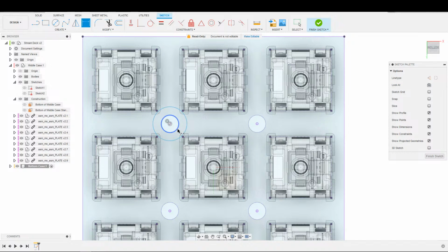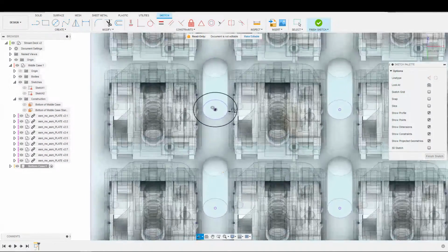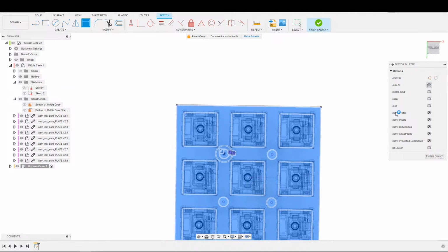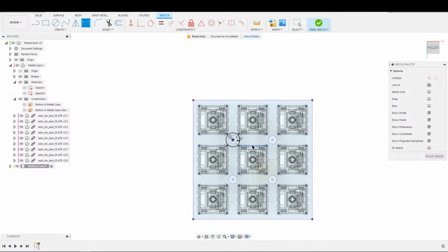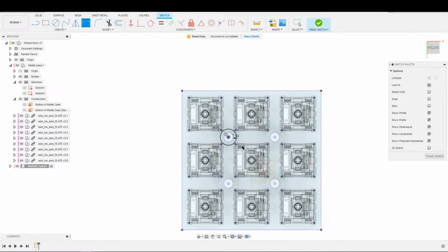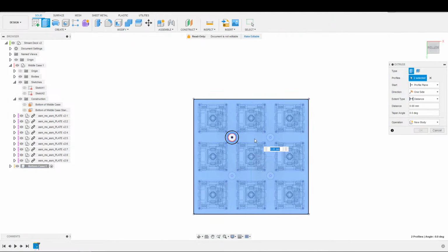Now we're going to want, I'll go 1.5 because it's not really doing much. All it is is getting us right in place, because again, the middle case is going to be sandwiched, so the middle case isn't actually going to be sliding back and forth against this peg, which means that this doesn't have to be particularly thick because it's not supporting anything. It's just to keep us centered. So that's all it's doing. Otherwise, let's go ahead and extrude this out.